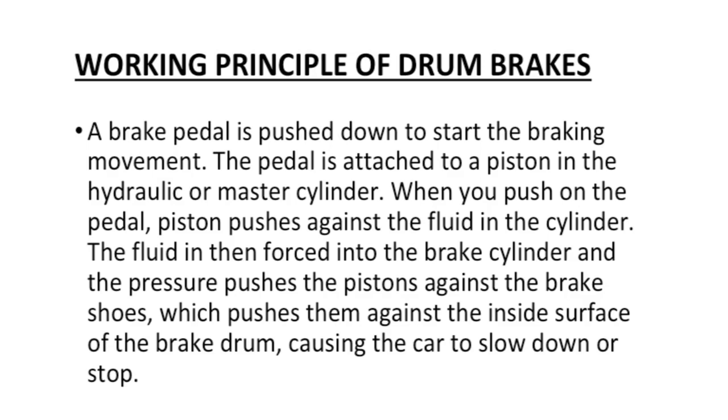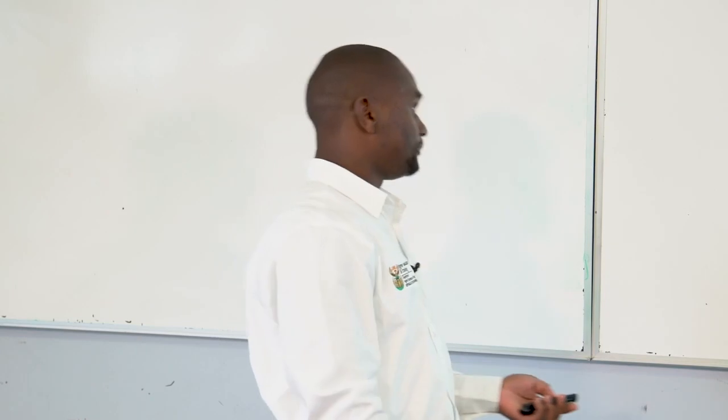When you push on the pedal, the piston pushes against the fluid in the cylinder, then the fluid is forced into the brake cylinder, and the pressure pushes the pistons against the brake shoes, which pushes them against the inside surface of the brake drum. This will cause the car or the machine to slow down.